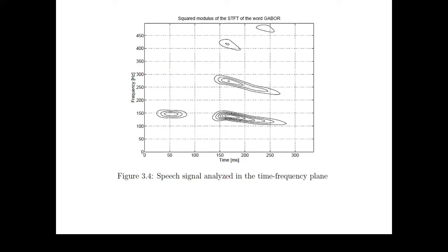If you look at this STFT with the Gabor window, at this location you should get a mean frequency or mean amplitude, or mean time period. However, there is a spread in the time domain and a spread in the frequency domain. This is your time spread and frequency spread, and the mean point is called the mean time or the average frequency.